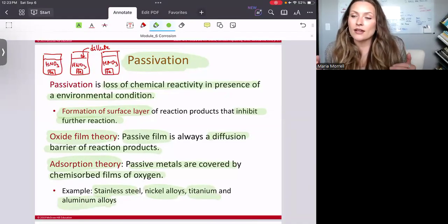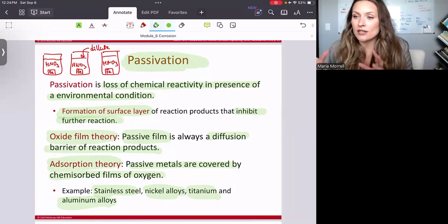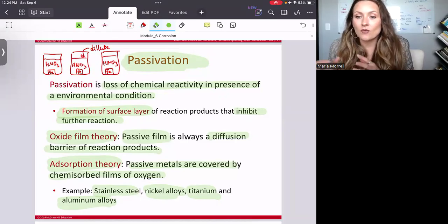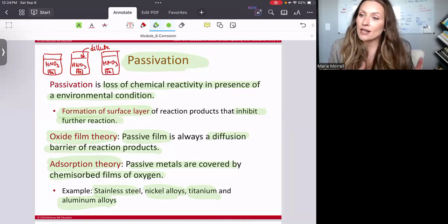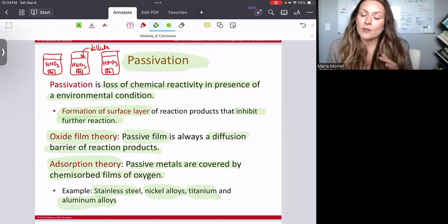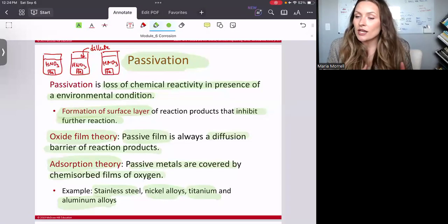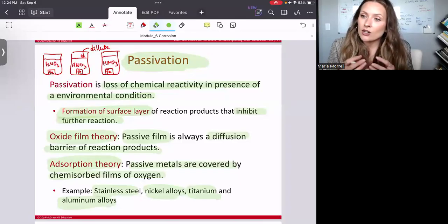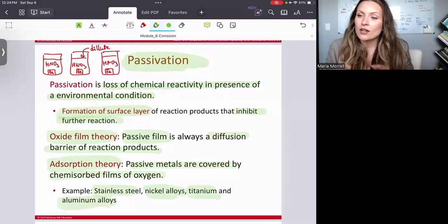And this is why, as an engineer, when you're doing your plant design or designing a process, whenever you have to deal with very, very strong oxidizers, I'm referring to acids, we often opt for something like stainless steel, right? If we have to. There are cheaper options such as polymers or ceramics, but stainless steel is a metal, yet we can use it for storage of highly corrosive fluids because it has this passive behavior under certain conditions, right?